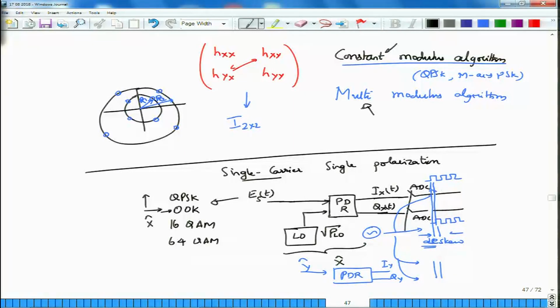So, after we have sampled them, what we get is a complex sample. Let me just combine them here right away after multiplying the Q component with j. Of course, in reality I am not going to multiply anything with a complex number. This is just for my intuition. What I do obtain is a complex number, yes, but that will be represented as two real numbers in the processing unit. Anyway, for my convenience and for our consideration, consider this to be a complex sample.